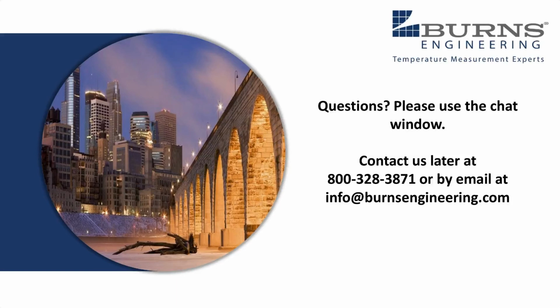So this is Jeff again. One of the ways to understand time constant versus time response is that time constant is the way all response times are spec'd out or reported on any kind of sensor. Time response, on the other hand, is what's actually happening, how long it takes in your particular process. The diameter of the sensor, whether or not it's in a thermal well, what the material is, all of those things factor into what the actual time response is.